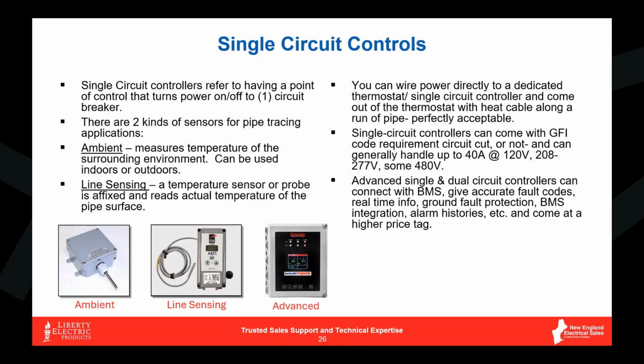When you get into stuff like the advanced controllers, if you want to be able to monitor things with BMS, or this is critical lab stuff going on, or process, where I'm very interested in knowing exactly what the temperature of that pipe is right now, because I can't have it below, say, 81 degrees, or whatever is in it starts to solidify. That's where you're looking at something more like an advanced controller that can give you particular set points and high current alarms. You can also have the advanced controllers do ground fault protection, which is a great integrated feature.